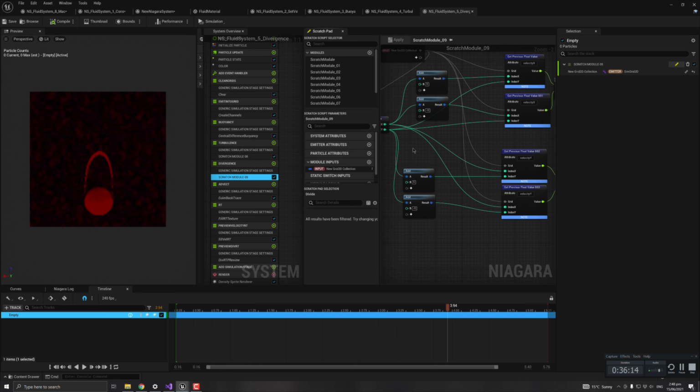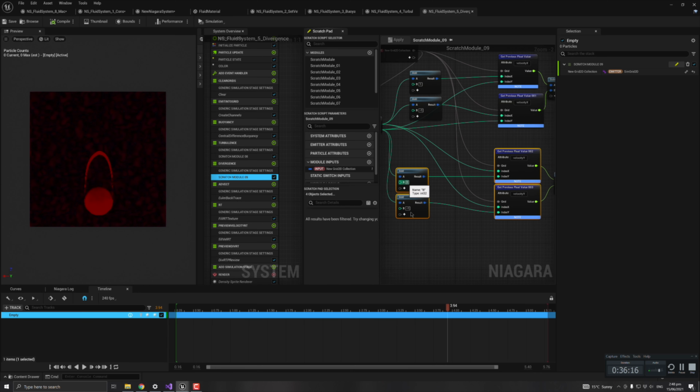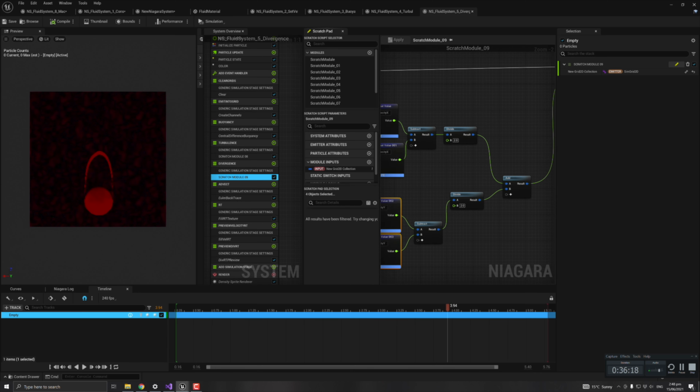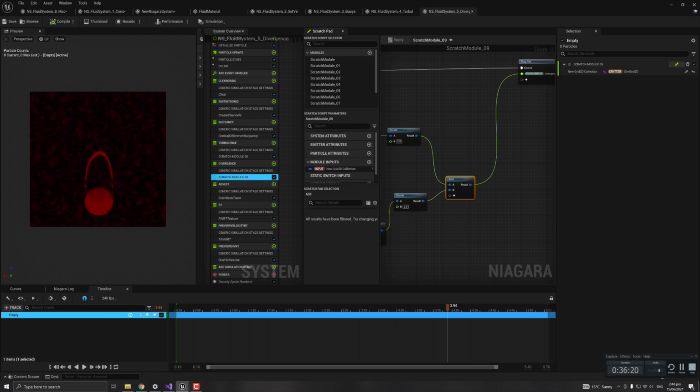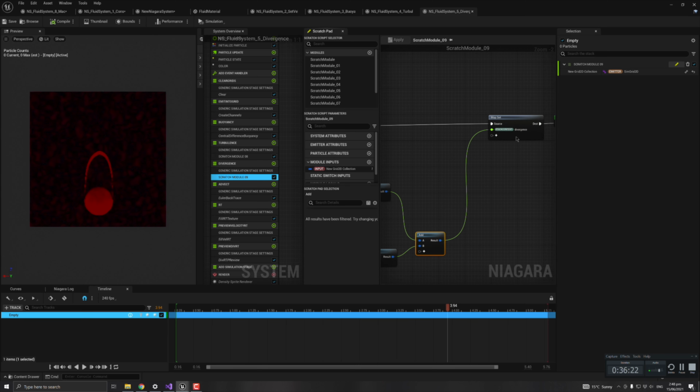And then we do the same thing for the y direction. We just sample above and below, and divide by 2, and then we add those two things together. And that is our divergence. It's as easy as just measuring it and writing it to a channel. And then we can actually use this divergence in the next one, which I'll show now.